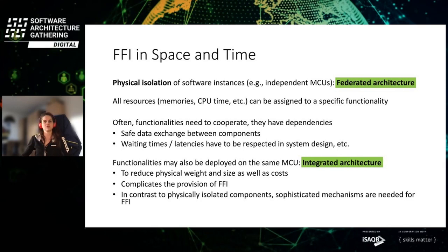So you have various electronic control units, these ECUs, with the CPUs on them in the car network. And the individual functionalities were pretty small and isolated from each other. But having all these devices in the car is also costly. It consumes space in the car, and all these devices have to be interconnected with each other. And this cabling is also pretty expensive, and it's pretty heavy. For example, there are over 50 kilograms of copper in a car for cabling, and they would like to reduce it.